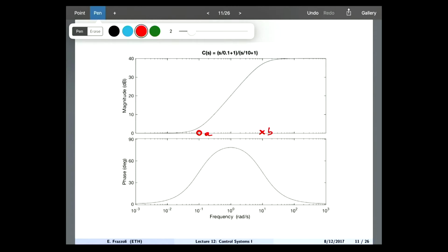A comes first, so the 0 comes first, so you go up in the magnitude plot first, and then you go horizontal again, okay? So this is the effect. This is how your loop transfer function will be reshaped, okay? So nothing happens up to the frequency A, then the slope gets moved up by 20 dB per decade, and then down again and goes flat, okay?